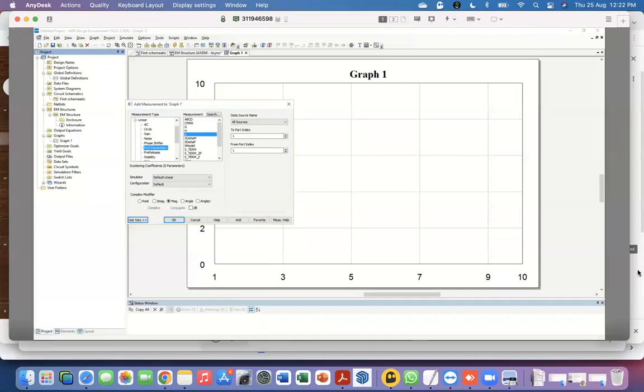The x-axis is mostly always frequency, because we are always looking at these as a function of frequencies so that we understand how the response changes as a function of frequency. So you cannot plot both real and imaginary on one axis. So you can choose real, imaginary, magnitude, angle, and there's something called angle U, which U stands for unwrapped, and we will discuss that later.